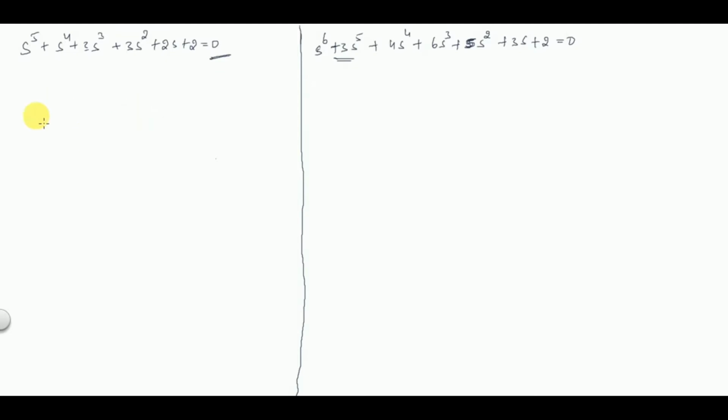Right. So first of all we have to construct the Routh array, so that is common. s power 5 is the highest order, so 1, next is s cube, next is s. Coefficients are 1, 3 and 2 respectively, odd powers of s. Next is even powers of s, which is 1, 3 and 2 again. So s cube will be a row of zeros anyhow, because when you have the same rows then it will be a row of zeros. Row of 0 occurred here.